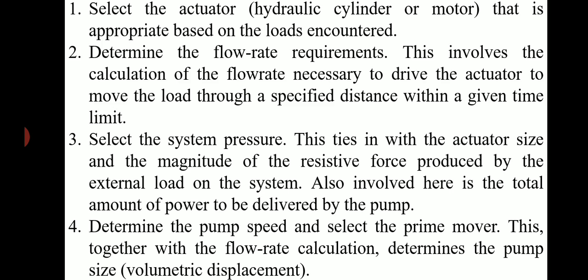Third one, select the system pressure. This ties in with the actuator size and the magnitude of the resistive force produced by the external load on the system. Also involved here is the total amount of power to be delivered by the pump. Fourth one, determine the pump speed and select the prime mover. This together with the flow rate calculation determines the pump size, which is volumetric displacement.